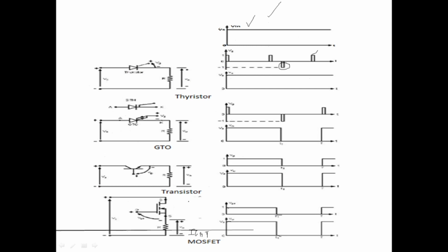So he mixed the good characteristics of transistor and MOSFET and made a new device called the IGBT, where the switching speed is better than the transistor and the on-state loss is better than the MOSFET. So it has moderate switching losses and moderate on-state losses. The IGBT is extensively used in power electronics.